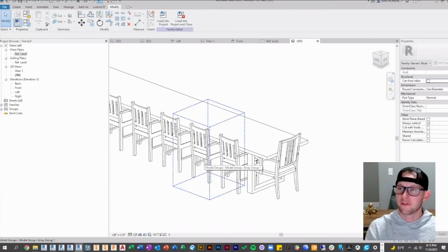And that's pretty powerful depending on what you're trying to create. You can preload, but there's a lot of caveats that go with that. I'm not going to go into them now, but if you do it blindly, you could end up hurting yourself, but it's really useful when you follow some rules. Yeah. And that's one of those things where a lot of people have seen families where you can change types, but just showing how you add the parameter, I know when I'm teaching people, no one ever notices that. When you have a nested family, if you click it, you can actually add the parameter to it. So that's awesome.